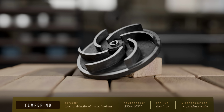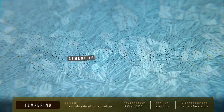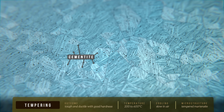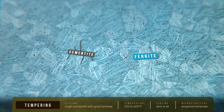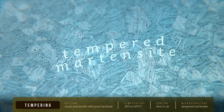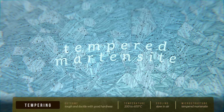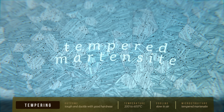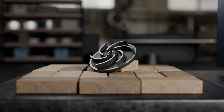During this tempering process, excess carbon atoms trapped in the distorted, supersaturated martensite lattice diffuse out and combine to form extremely fine particles of cementite, allowing the BCT martensite lattice to relax back towards a BCC ferrite structure. The resulting microstructure is called tempered martensite. This transformation greatly improves the ductility and toughness of the quenched steel, while still retaining much of its strength and hardness, thanks to the finely dispersed cementite particles. Steel in this quenched and tempered condition is usually referred to as hardened steel.